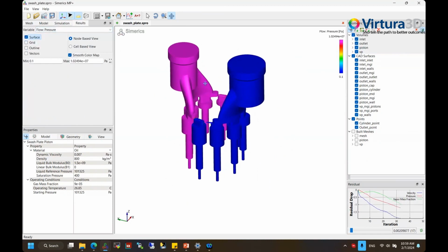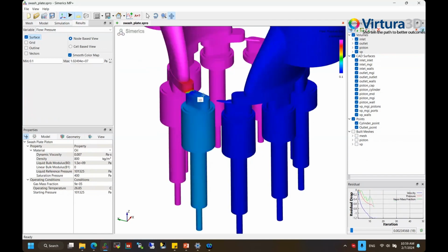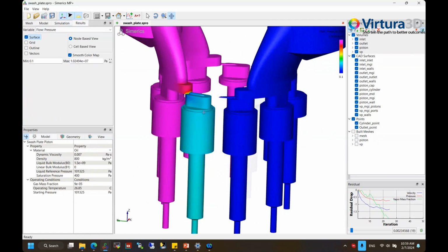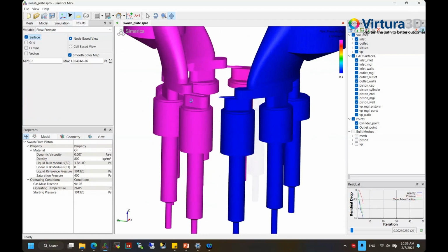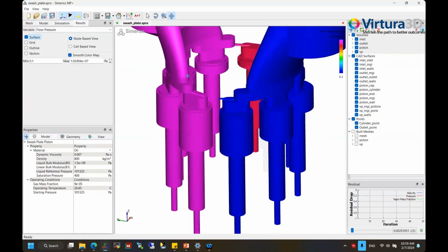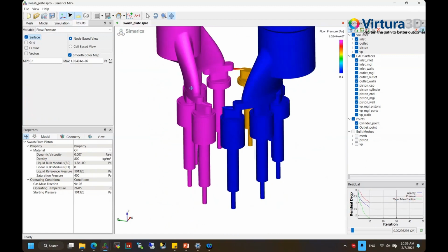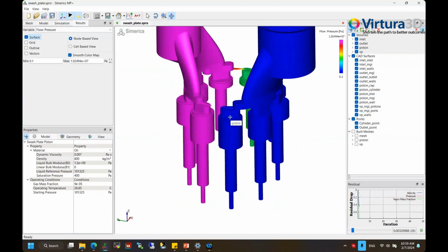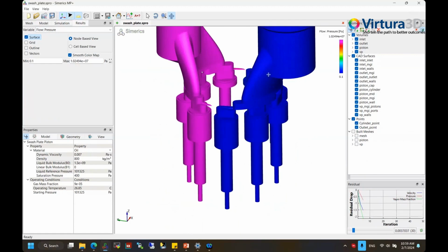This is how the pressure looks, and you can see we have a high pressure at this discharge port. As this piston moves, what you will notice is that first, this piston is compressing, but the pressure is not compressed enough yet. At the same time, these pistons start to touch this high pressure part. So what's going to happen when you have a high pressure part and a low pressure piston? You're going to create a very strong jet, and that jet will shoot into this piston, and that will generate the cavitation bubbles.